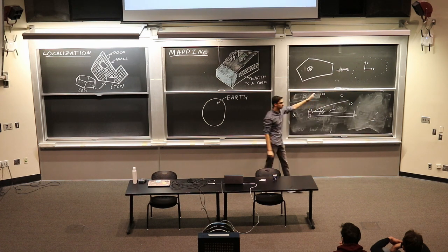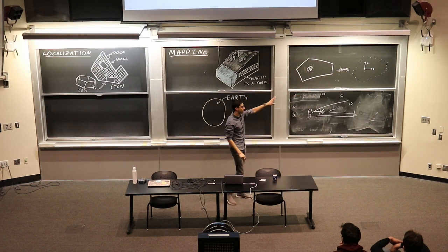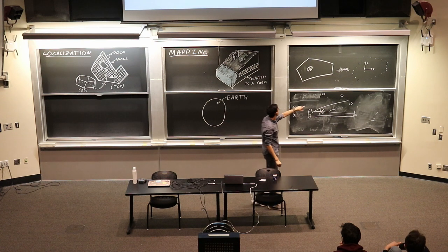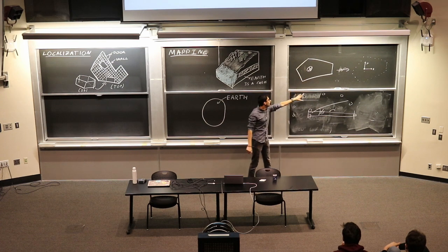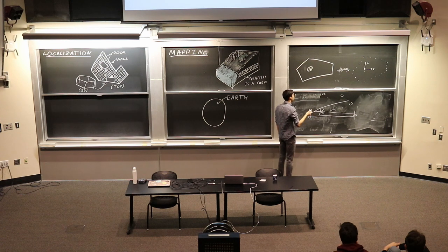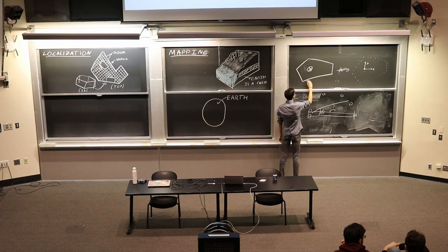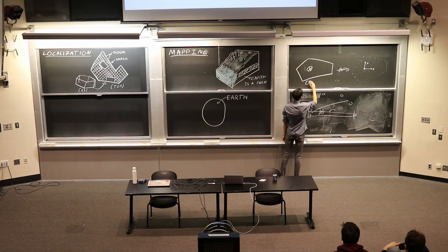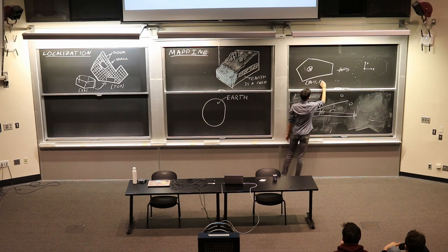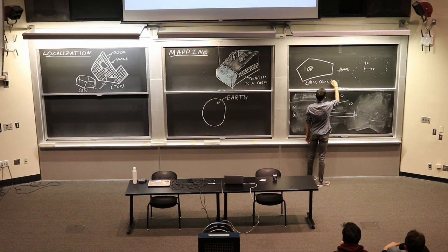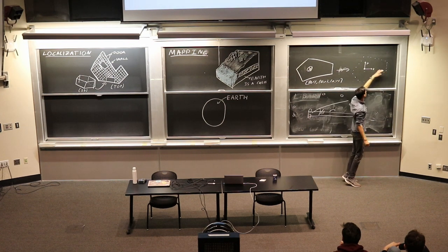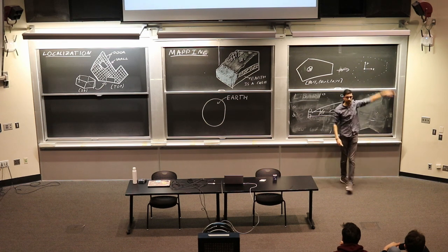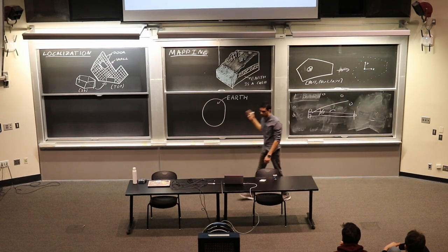Now that's a very low resolution point cloud because I don't want to draw 1,000 points. But this is what you tend to get out of a LiDAR. And how this is usually stored in a computer is they usually will give you a list of theta-R tuples. Because at this theta, you're at this distance R, at this theta, you're at this distance R, and so on and so on, and that's what a point cloud looks like.